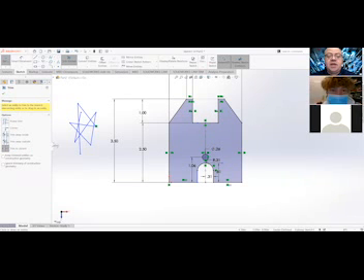When you have that on, you put your scissors right by the line you want to remove, and it takes it out. So you can precisely remove little lines that you don't want. On our drawing, that was this line here and here, because I had the center line, I had to trim that out. There's also the vertical line that came up and the vertical line that came up here. I just trimmed them down to the circle.